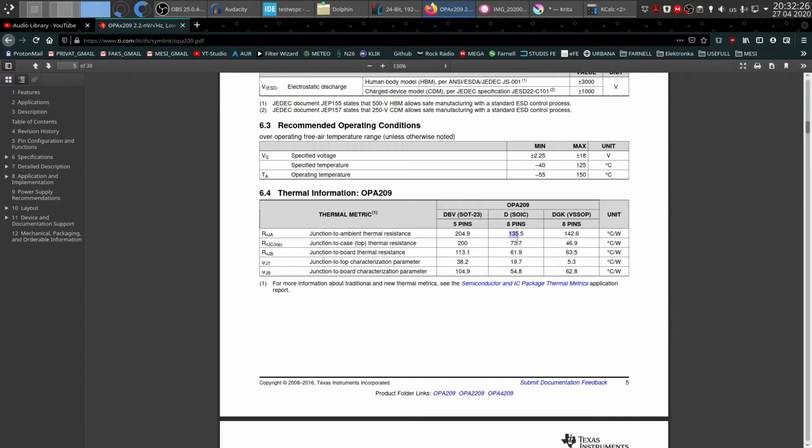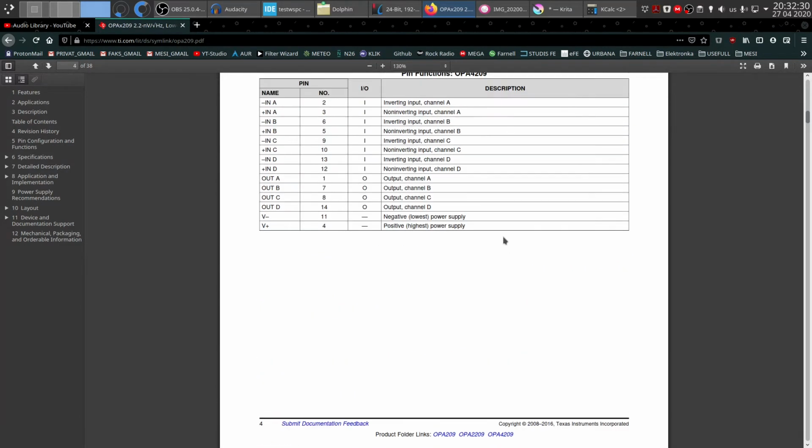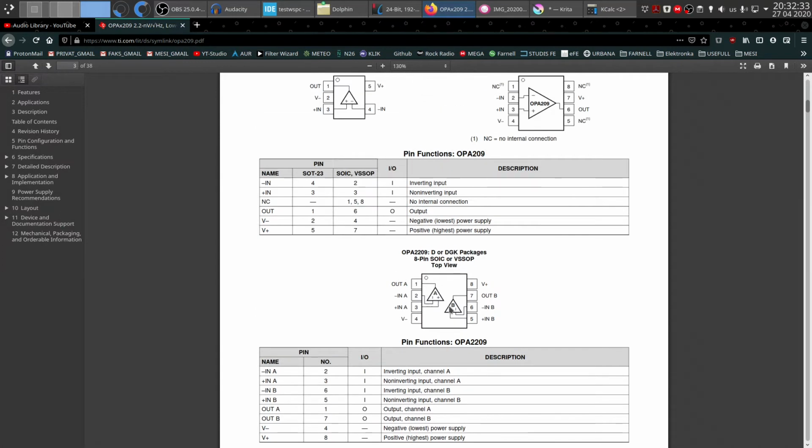And that's basically it. But if you have a dual amplifier package, the one that has 2 amplifiers in it, you can guarantee that these two will be much more similar than 2 of these ICs bought separately, because these two were generated at the same time, at the same temperature, in the same foundry. Therefore, these 2 amplifiers should be more similar than 2 separate ICs. That should result in more consistent performance characteristics.